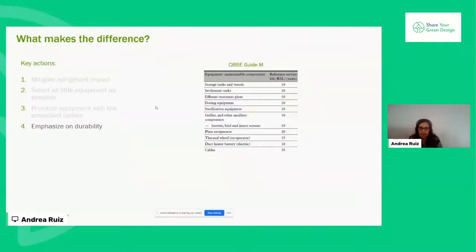Finally, listing in here for you the durability. Even though in the C1765 we skip the part of how many times we replace the equipment, this will be used at the final end value of the whole life carbon. An example of this could be having an idea through the CIBSE Guide M, or other guides used in other parts of the world, for the lifespan of an equipment.